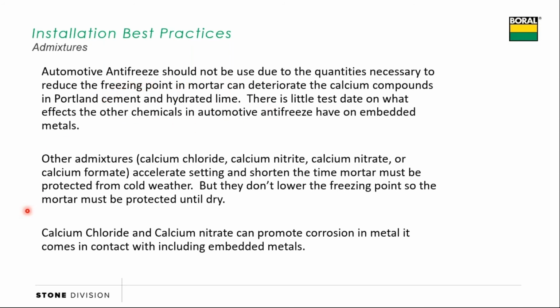So please don't use antifreeze, and please be careful with calcium chloride and calcium nitrate. They do promote corrosion in metal. So be careful around metal door frames, window frames, and especially if you're using metal lath, you don't want to contribute to corroding your metal lath.